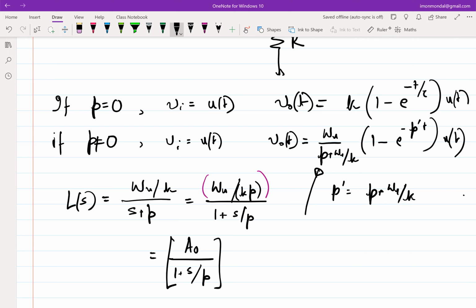Yes. So the conclusion is that the frequency beyond this omega u by K will have the ideal nature of the integrator, but due to less feedback, the desired output is not exactly met. Correct. But at low frequency, although there is no ideal integrator nature because the response is flat, the feedback strength is high, so there is a negative feedback nature. Negative feedback works if the loop gain is more than 1. Negative feedback doesn't work if the loop gain is less than 1. That's the crude way of distinguishing.